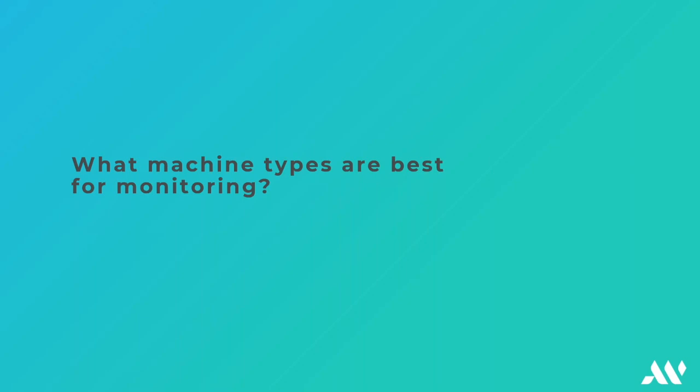There's a few out there that we don't like to go on that are not good for continuous monitoring, but for the most part it's going to be AC, DC motors, pumps, gearboxes, chillers, compressors, fans, all the basic types of rotating components. But you always want to start with your most critical and then work your way down.